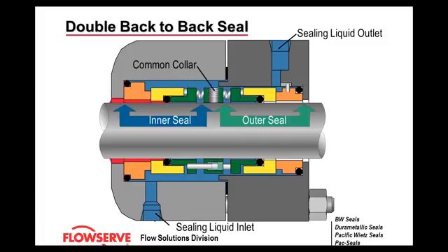That fluid is generally used to collect leaked process stuff from the process. Could be anything like a gas of some sort, and then it needs to be vented out to the seal pot, and then it's vented to flare. Or if it's pressurized, it provides lubrication to the seal faces, especially if the pumped fluid is overly dirty or does not have very good lubricating properties.